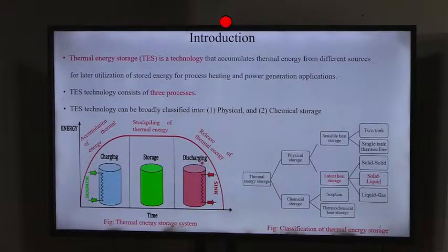If you are having this relation, then at a temperature say beyond 45 degrees centigrade, the power generating capacity, or the electricity generation from a PV panel, is quite diminished, and which actually does not suffice our needs. Then what do we look for? We look for some sort of cooling of the PV panel by circulating some sort of coolant on the back side and then extracting that heat.